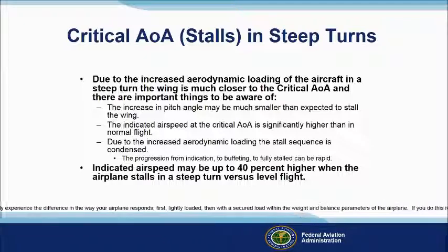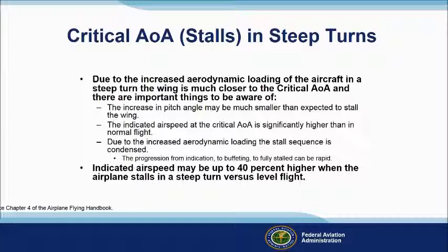First, lightly loaded, then with a secured load within the weight and balance parameters of the airplane. If you do this regularly, you will not be so out of breath when you take a load of friends out for that $100 hamburger some late summer afternoon. Reference Chapter 4 of the Airplane Flying Handbook.